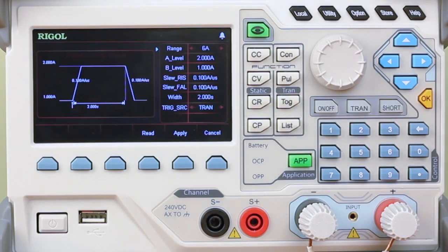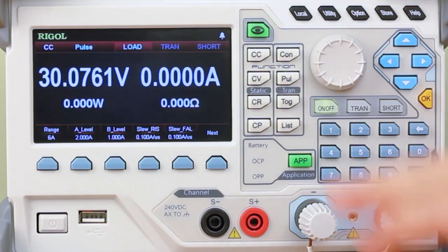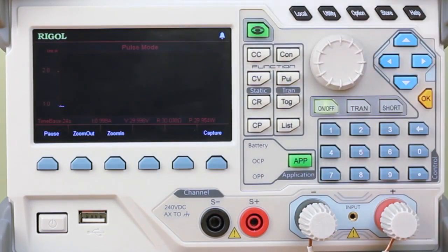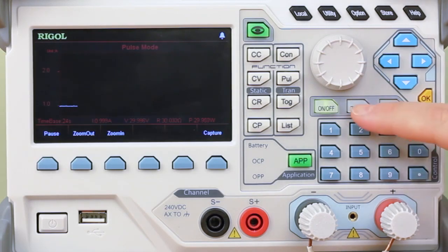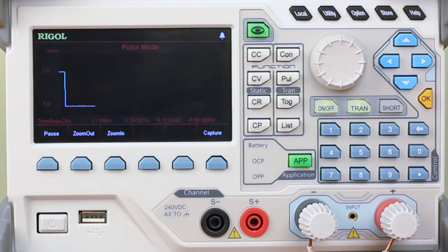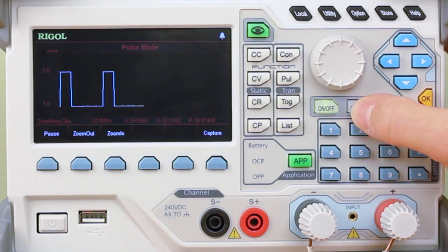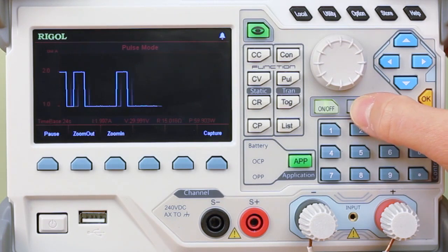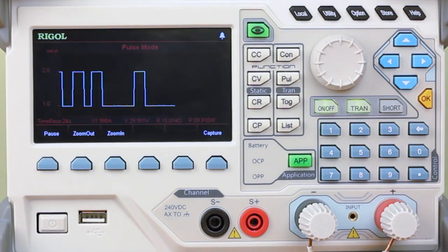Now let's look at pulse mode. While continuous mode works continuously upon one trigger, a pulse mode requires a trigger for each period. Here we have the same settings, except we have a 2-second pulse width instead of a very fast pulse width. Let's activate this, change our view, and as I trigger a change, you can see pulse mode holds the 2-second pulse and then waits for another trigger. And I can trigger it at whatever rate I need to manage the loading that I require.